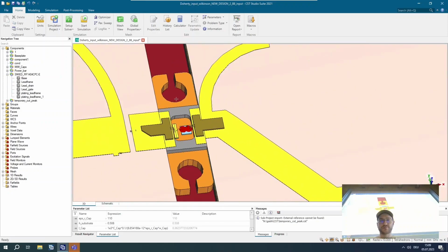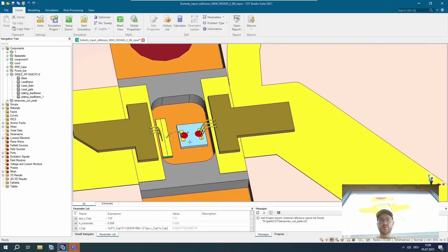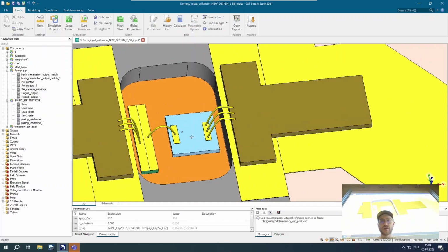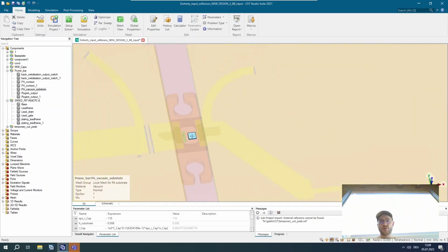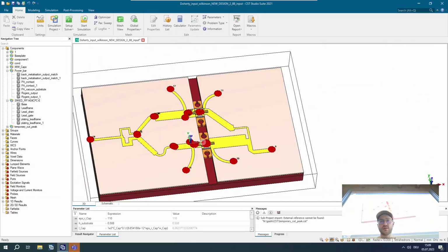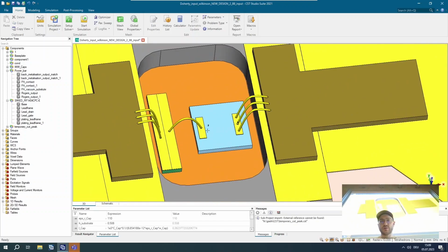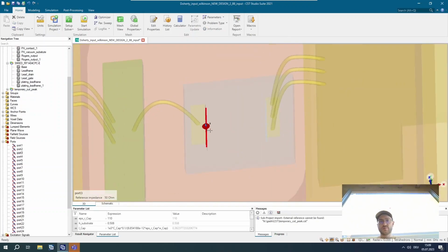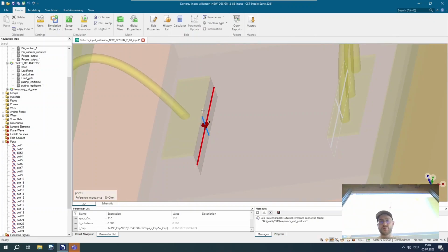You have here a certain package for the die, for the transistor bar. This is an example of the transistor bar. The transistor bar is later on added into ADS. So you basically have a 3D structure that is a vacuum only, just to hold space there. And then you have a transition port definition. You can see the port definition here, from the top of the conductor. This is the gate pin. As I said, we have these capacitances that are induced due to the gate and the drain pins.